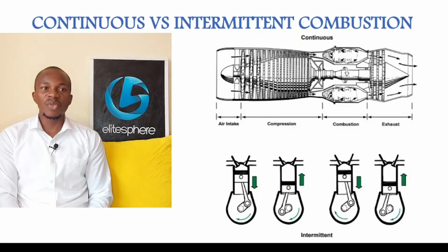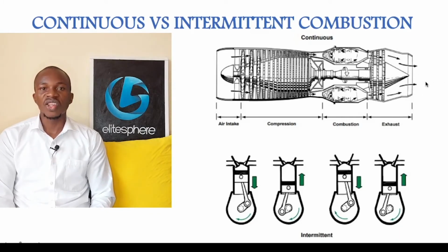On a gas turbine engine, the process starts by air flowing through the intake into the engine. From the intake, it goes through the compressor where it is compressed. From the compressor, compressed air goes through the combustion chamber where fuel and heat is added. From the combustion chamber, the air goes through the turbine where the energy to drive the compressor is derived. Then from there, the air is expelled rearwards through the exhaust of the engine, generating thrust.